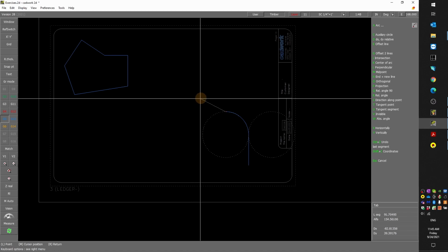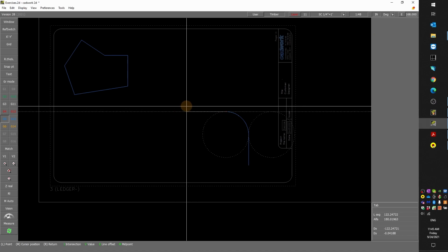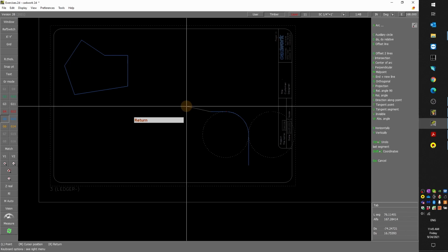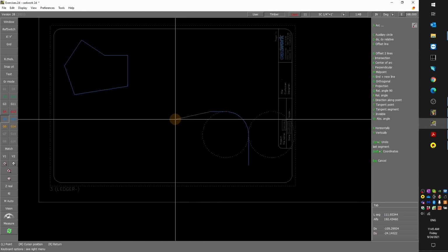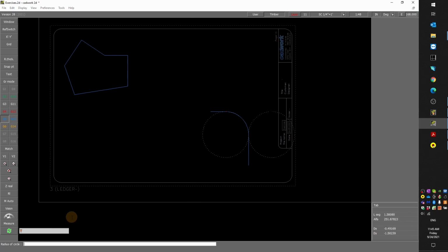Then I need to go in the X direction, so towards the left, so minus 4 feet. And we can continue with another arc of a circle, so A, and then another tangent, so T, with a radius of 10 feet.